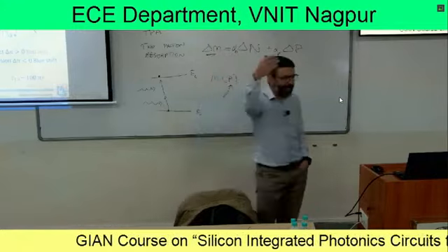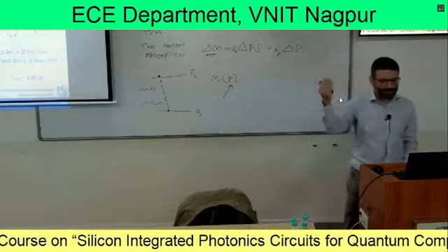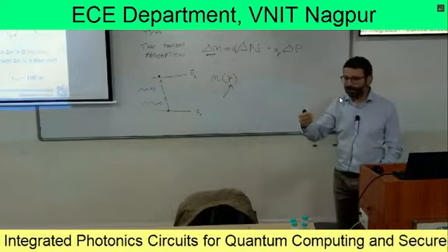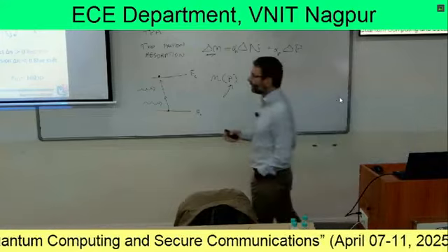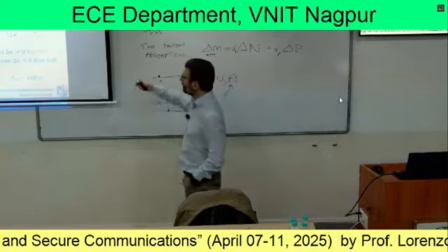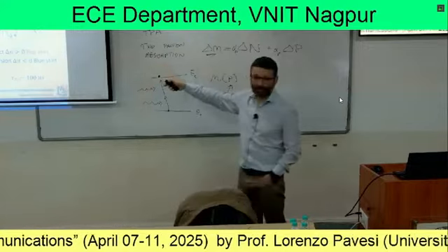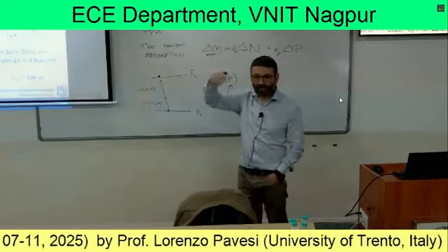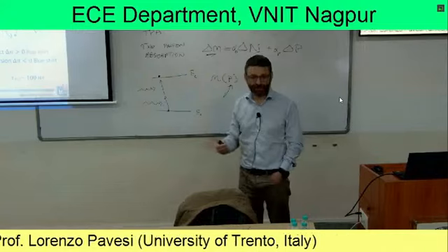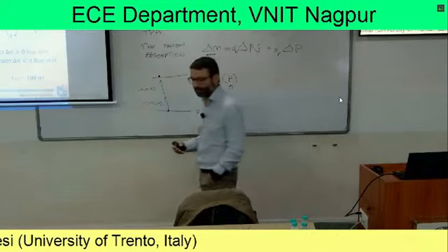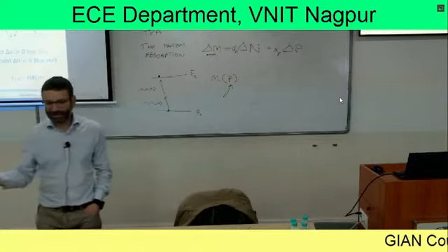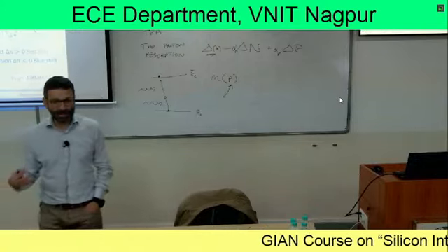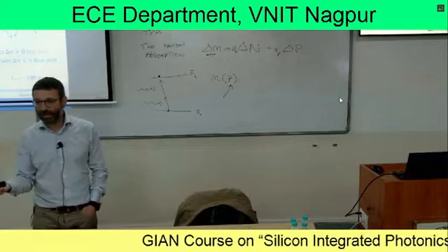But then those electrons and holes thermalize, meaning that they lose the extra energy. In the thermalization process, they emit phonons, so we have multi-phonon generation inside the semiconductor. The phonons are lattice vibrations, so the lattice starts to vibrate, meaning that the temperature of the lattice is increasing.